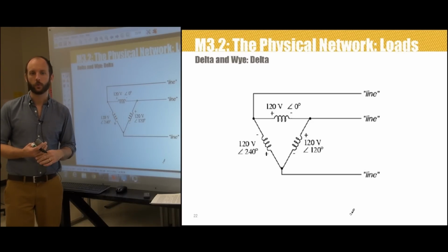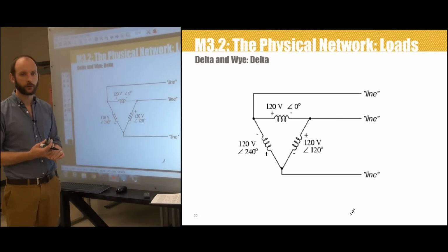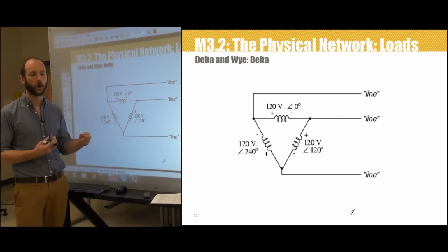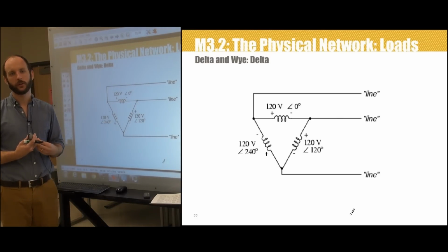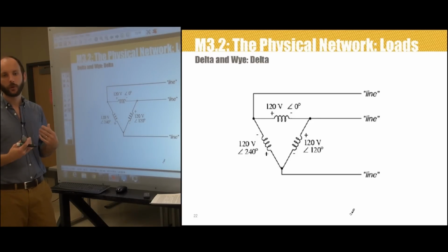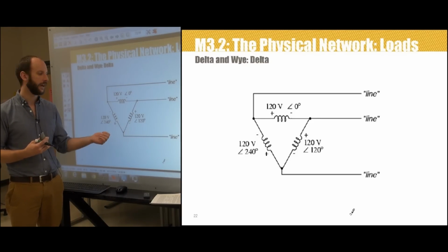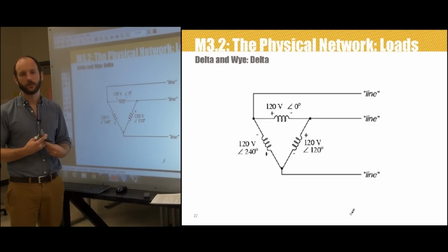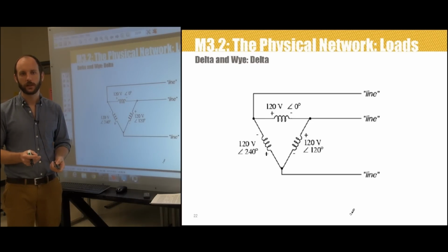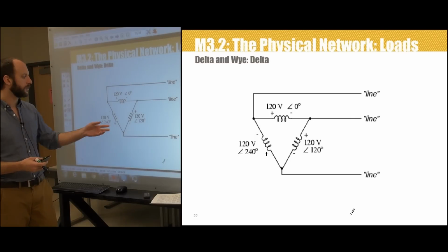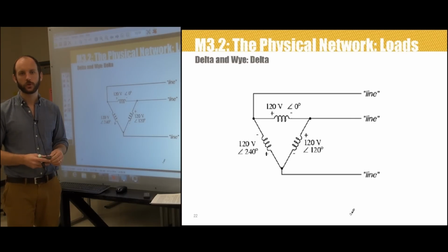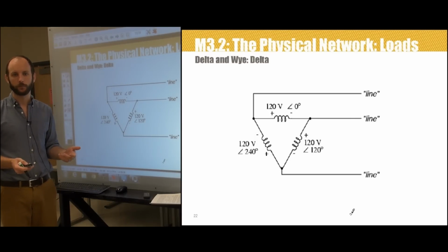As a whole there is no reference node, there's no ground node. The entire delta circuit can therefore float at any arbitrary value of potential. And therefore, if any part of the circuit accidentally gets grounded, which would normally cause an outage, the delta circuit can continue to operate on an emergency basis. You therefore often see delta circuit configurations used where reliability is the most important.